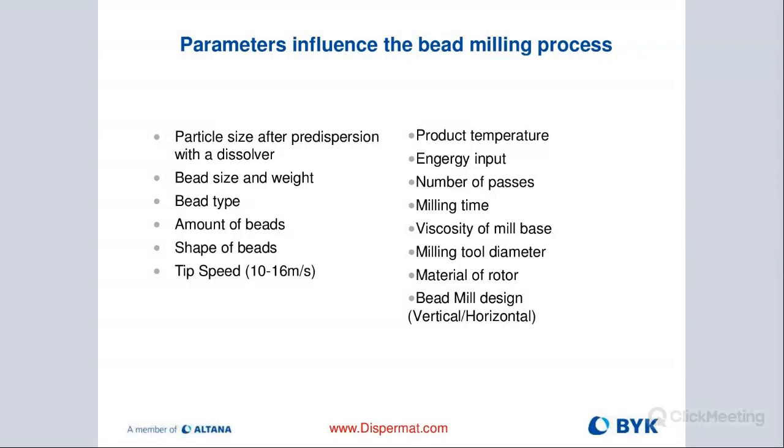Number of passes, how often does it cycle through my basket mill or my horizontal media mill? Milling time, very important. How long am I milling?